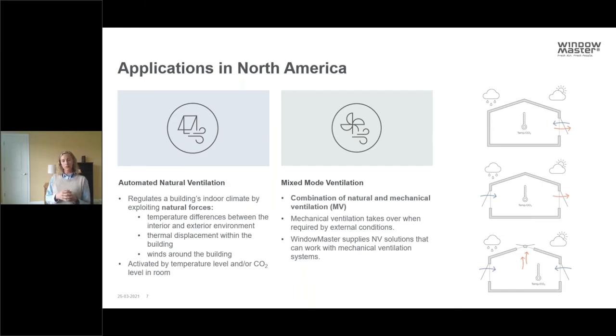What it also can be used for is something called mixed mode, or you might also hear me say hybrid ventilation. Now, if there's some mechanical engineers listening in today, they might say, well, Mia, mixed mode and hybrid ventilation, those are maybe a little bit different, but today I might use them a little bit interchangeably. If I talk about mixed mode or hybrid ventilation, I'm talking about using natural ventilation at certain times of the year or days or months, and then at other times using a mechanical system. So those are great solutions where natural ventilation is used through using window actuators.